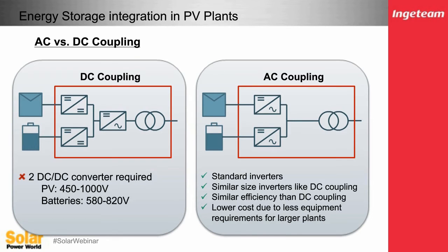And in the distributed system of a DC battery plus PV array, because of the different operating voltages of each individual component, the batteries versus the PV array, you would have the demand of a DC to DC converter and a common DC bus before the final DC to AC inverter connected to the grid.